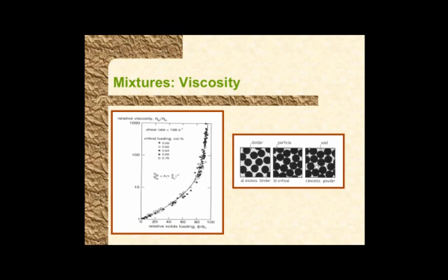If some regions of a batch have more powder and some regions have less powder, and you're doing mass manufacturing, some parts will be defective, some parts will not be defective, and the poorer the mixture, the greater the defect population, and there's nothing you can do to change it in the molding machine, right? And so mixing uniformity is very important, because of the sensitivity to changes in viscosity with small changes in volume fraction. That becomes a specific challenge to address.